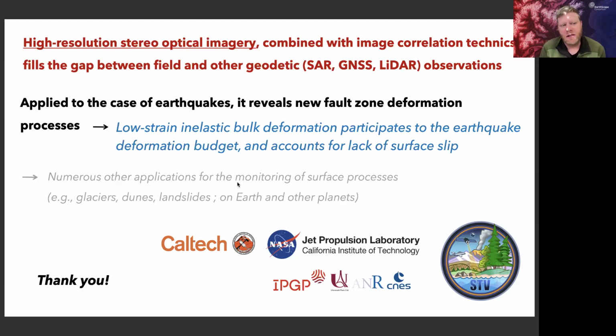In calculating the shallow stress perturbation and the potential inelastic yielding, did you consider depth-dependent variation in shear modulus or rigidity? And what is the rigidity value used for shallow near-surface depth?